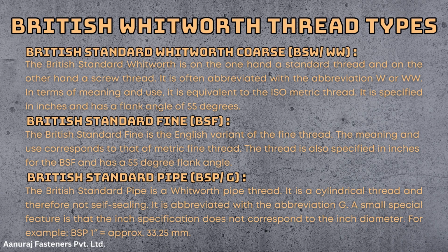British Standard Fine (BSF). The British Standard Fine is the English variant of the fine thread. The meaning and the use corresponds to that of metric fine threads. The thread is also specified in inches for the BSF and has a 55 degree flank angle.